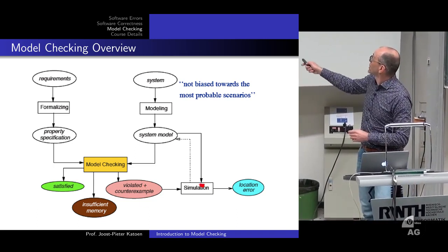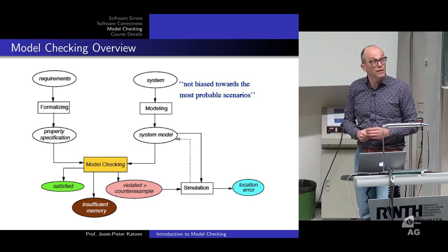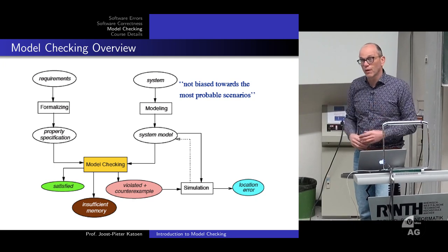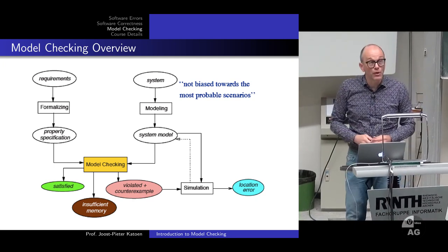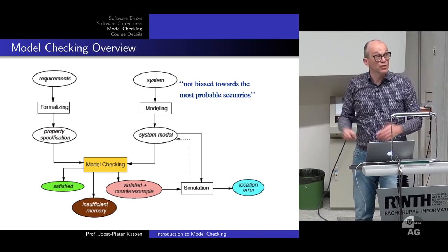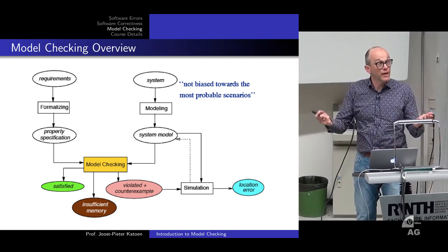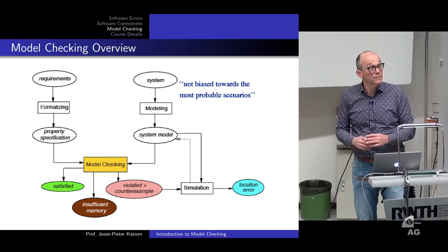So typically you get a counterexample, you can simulate the counterexample, hopefully get some information about where the bug is, and then this is helpful maybe to fix what you're supposed to do. Sometimes this means that you have to fix the model. Sometimes it turns out that you're not checking the property you want to check, so maybe you made a mistake here and you have to go back. And sometimes you found a real mistake. That's also possible.